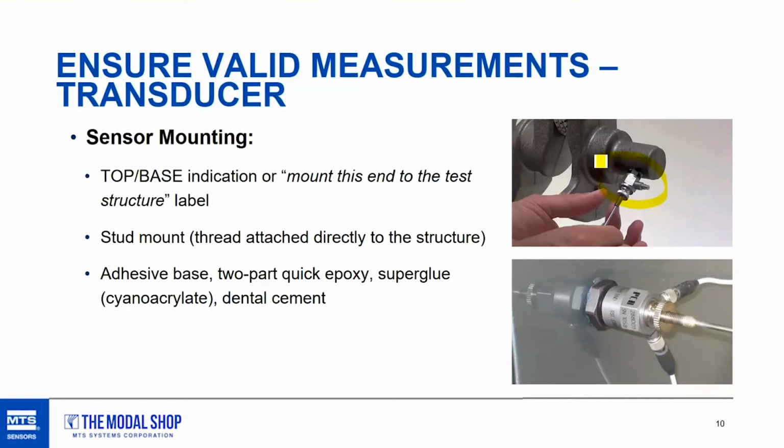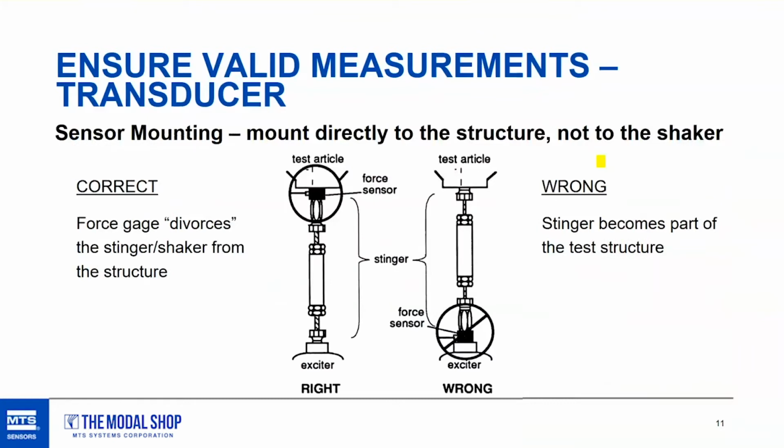And one common mistake we see a lot of times when it comes to shakers and stingers and connecting them to the structure is where to mount the sensor.